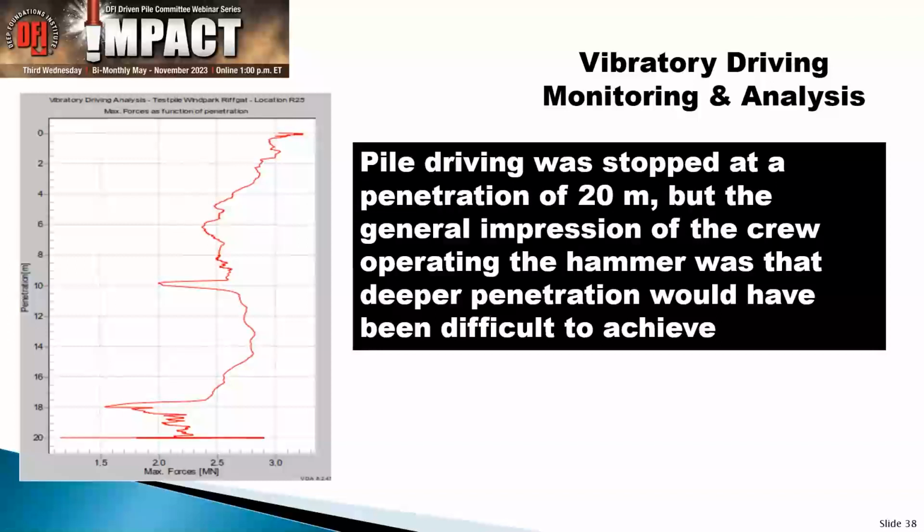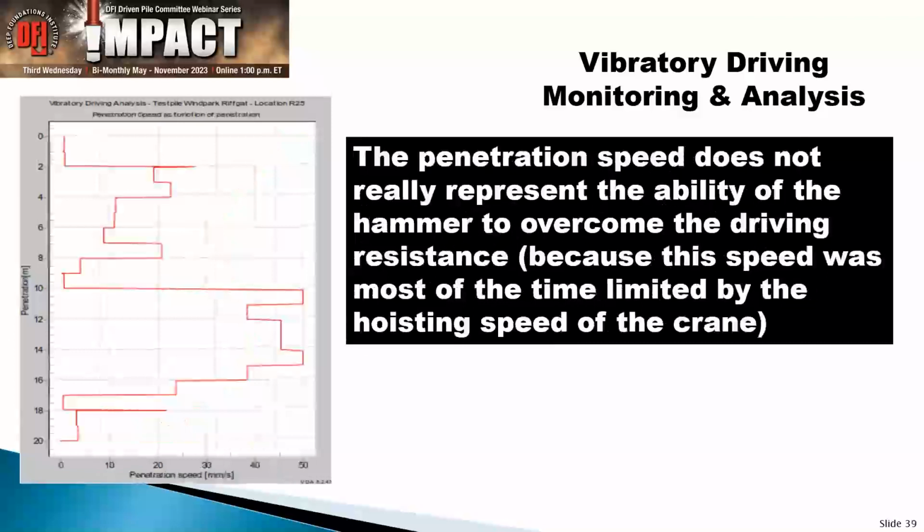So it was kind of like, well, it stopped. When you then start asking questions, it was kind of like, well, yeah, we stopped at the 20 meters. It was kind of hard, kind of difficult to drive. And we don't think that we would have reached the final penetration. Besides that, for that project, you had to use an impact hammer anyhow at the end to drive the final part, so they just stopped it. And that's the risk that you have quite often, that people make decisions and don't necessarily get you all the data. But clearly, we could not go as deep as what we thought we could.